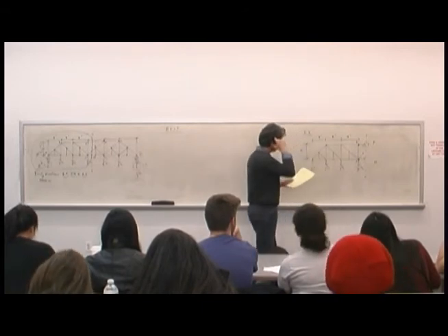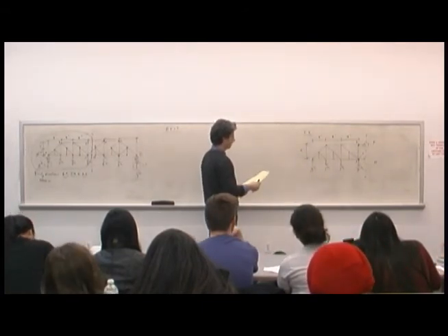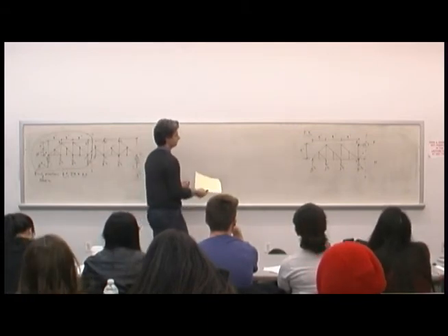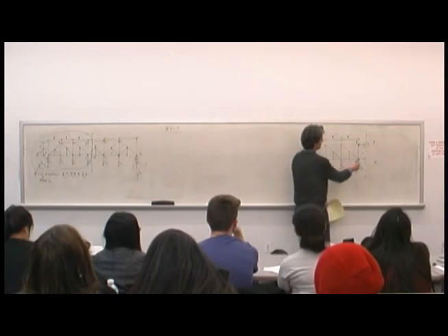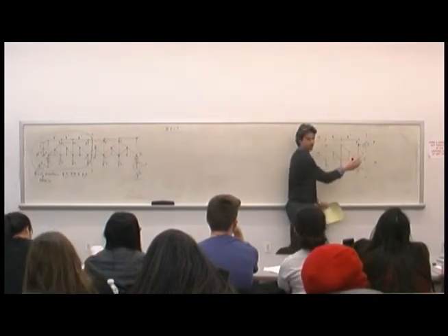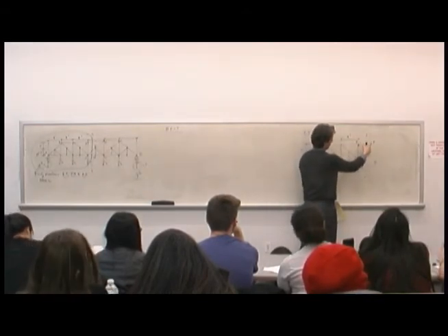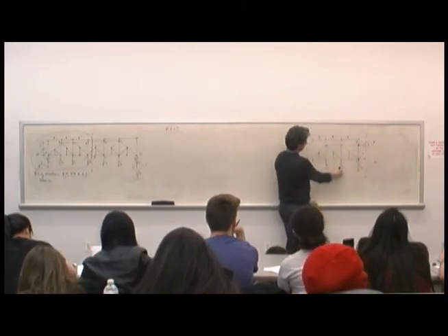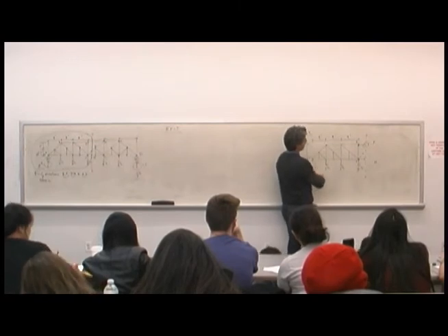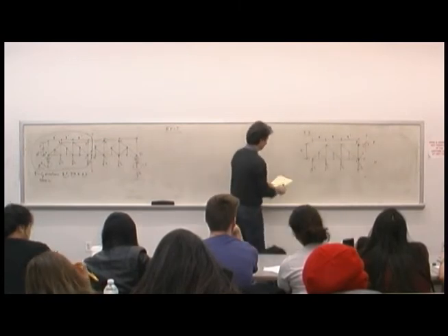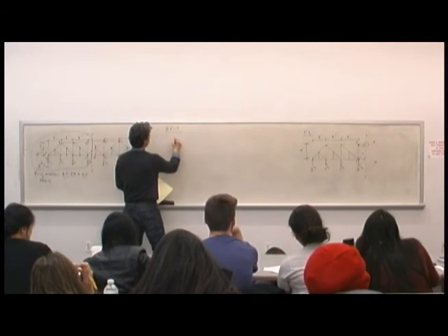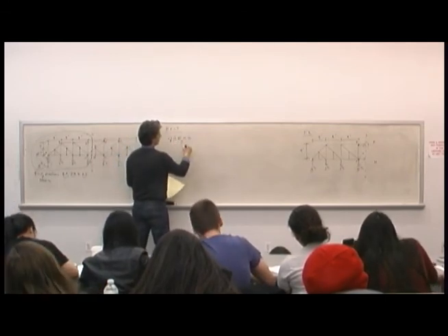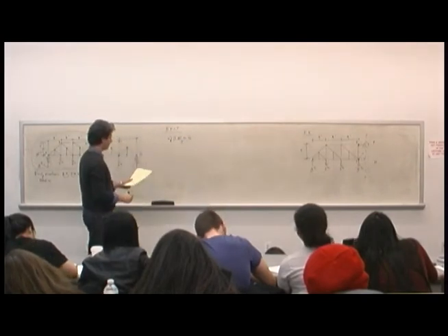What can I do? Sum of the moments at J. What happens? These two forces get isolated. I don't care about them anymore, and I'm just left with EF. This 5 kips goes away, so I'm just left with the 3 kip, the 2 kip, the reaction, and that 4. So I would do that. Sum of the moments at J equal to 0.